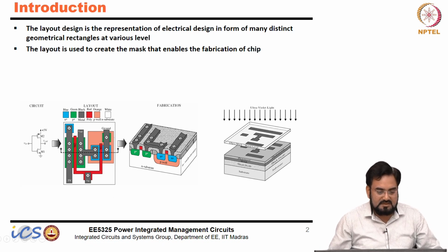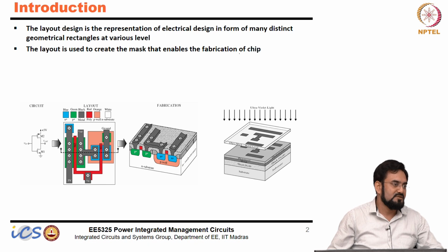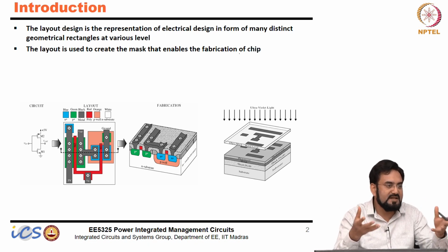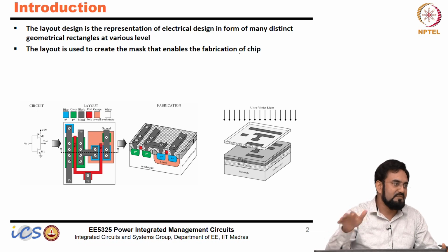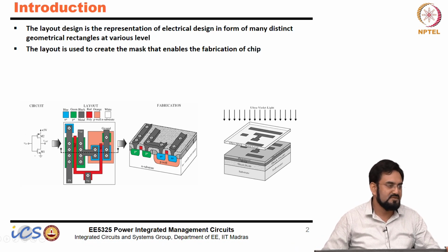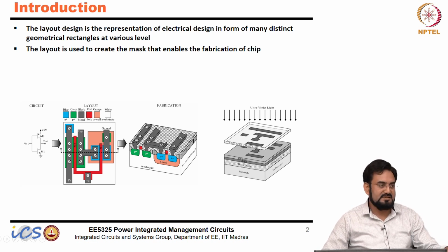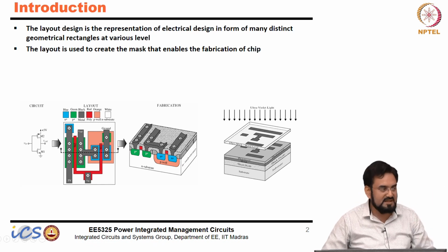So, the layout design is the representation of the electrical design in the form of many distinct geometrical rectangles at various levels. The layout is to create the mask that enables the fabrication of the chip, that is it. You are telling your Fab that this is how to create the mask, and they will create different masks and, based on that, fabricate the chip. They do not care what circuit you have implemented. They do not understand whether you have an op amp or anything else, they only understand the layers, and that is what you tell them. This is layer by layer information I am giving you, and that is how you have to fabricate, that is it.